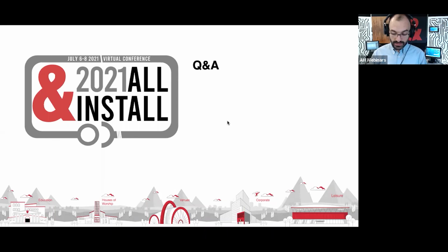Yeah, good question. It does, yes, and that's why I mentioned the use of the sound reinforcement output as opposed to just taking the same source and going straight into the amplification of the room, which you can possibly do. But particularly in larger rooms with a lot of reflections, if you can take the sound reinforcement output and use that one for voice reinforcement locally, that would also improve your, as you say, gain before feedback. And even attempt to basically suppress any feedback as it starts.